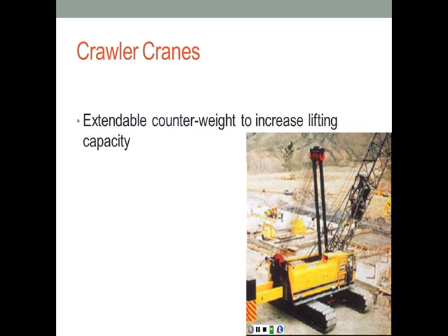And here's an extendable counterweight to increase the lifting capacity. The counterweight is here at the back of the crane, and the farther it can extend hydraulically, it offers better balance for the crane to counterbalance the load at the end of the boom on this side.